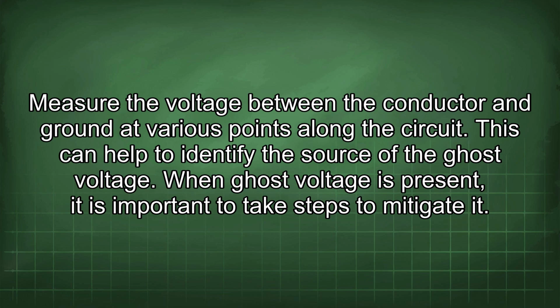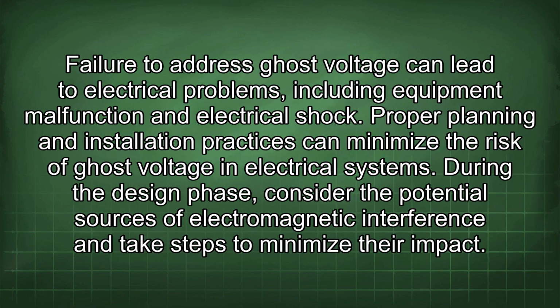Measure the voltage between the conductor and ground at various points along the circuit. This can help to identify the source of the ghost voltage. When ghost voltage is present, it is important to take steps to mitigate it. Failure to address ghost voltage can lead to electrical problems, including equipment malfunction and electrical shock.